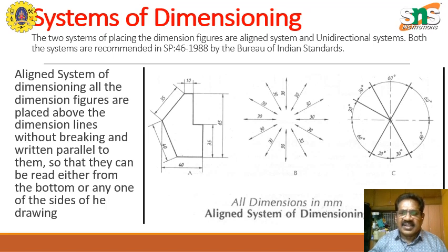Here, these are the radial dimensions. We pull out the dimensions, and if you look at this, as it goes down, we will not put the text upside down. We will write the text above the dimension line, so that it is easy for us to read it from the front. Okay, so that is the idea. This is an included angle of 60 degrees. There's an included angle of 30 degrees. Here at the bottom you have 30 degrees each. So we find out where we place the text of the dimensions.